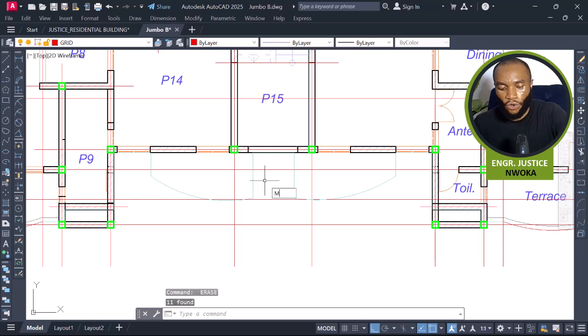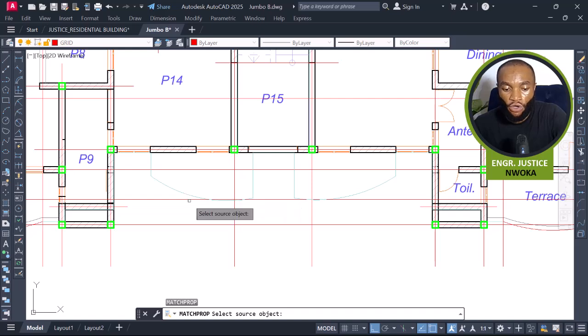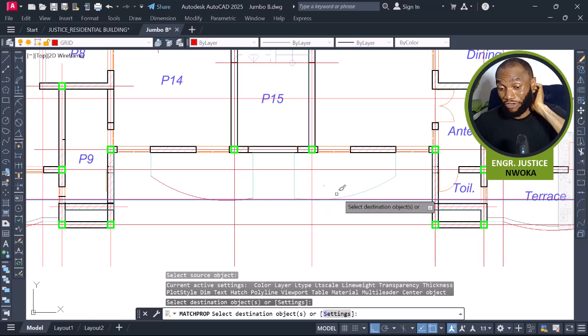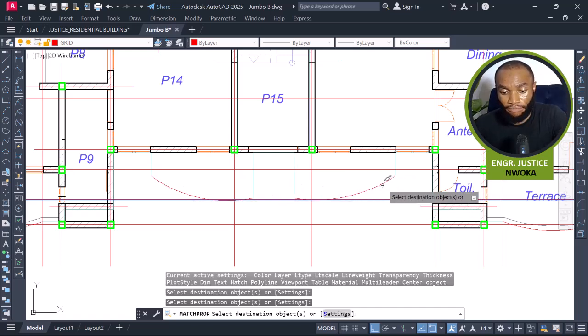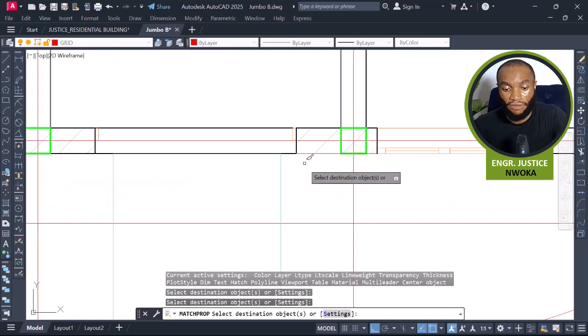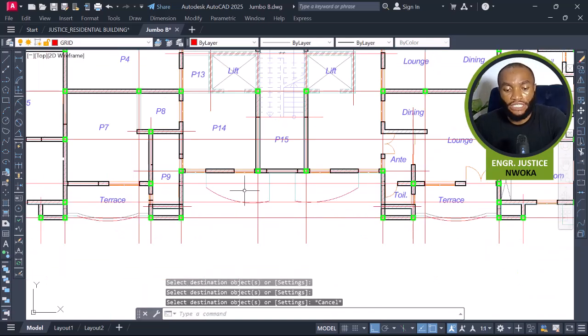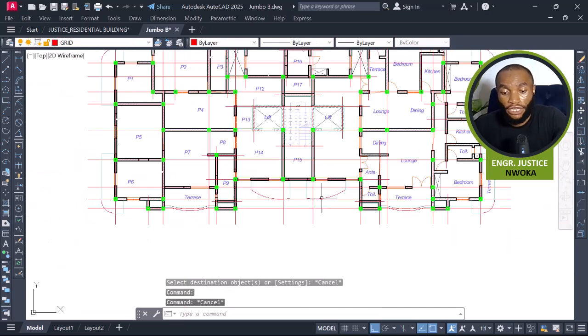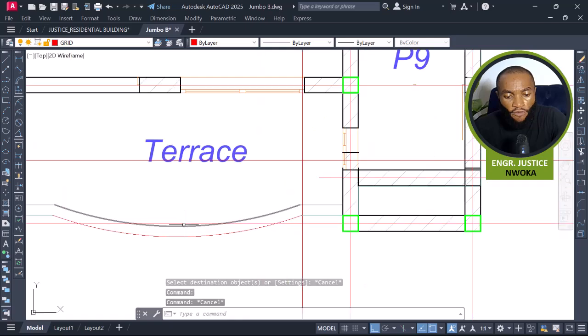Again, convert. Always have that habit to convert every curve to what? To grid line. Okay, that will help you to get the right modeling for the slab cantilever. Okay, that's fine. So with this now, we can leave this other one here. This is a straight line, which can be gotten from the software. Okay, so with this now, we have converted everything we need.